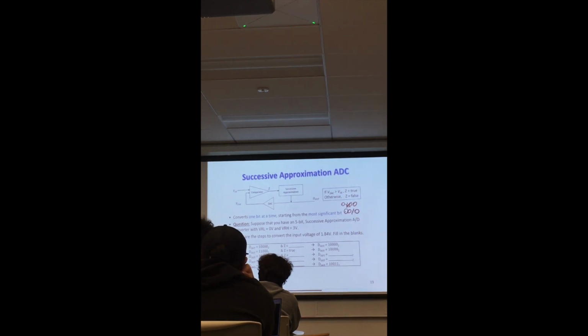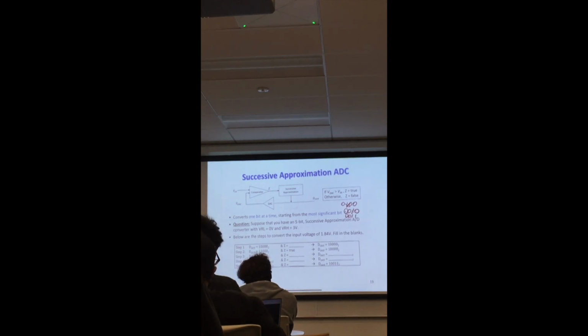And it will try another bit. Assume now that the value produces a lower analog value. It will say, okay, now I have to keep it, so the 1 will stay, and it will move on. Now these 3 bits are established. It will set the next bit to 1, again produce an analog value, and compare it with the given value. Is that clear?